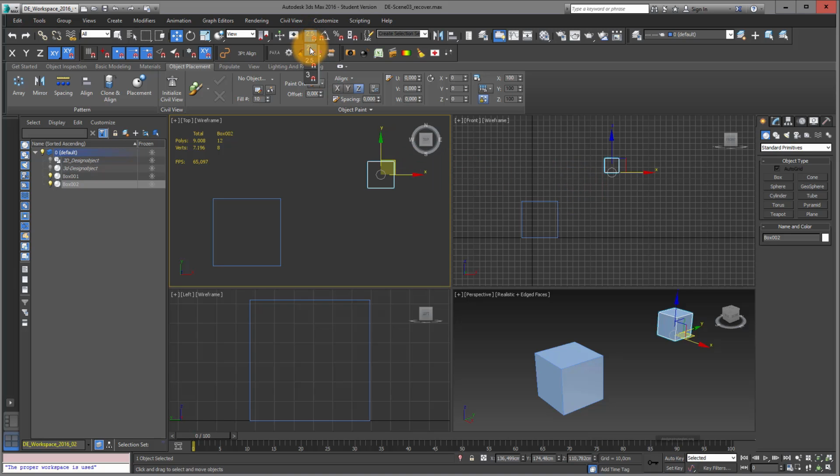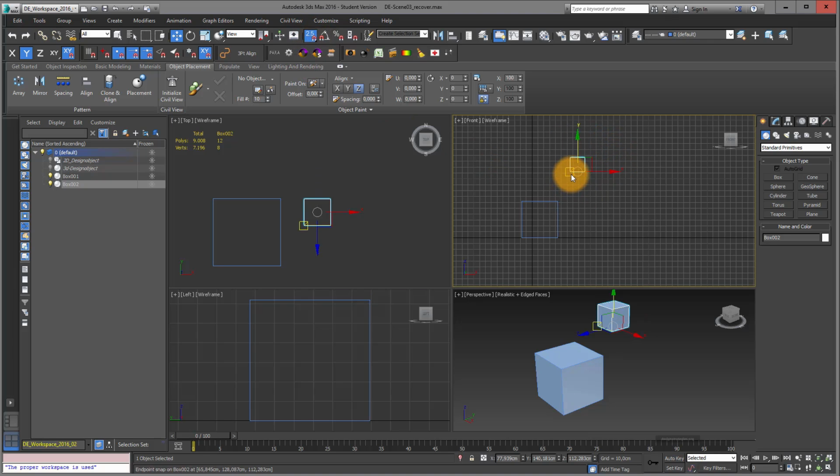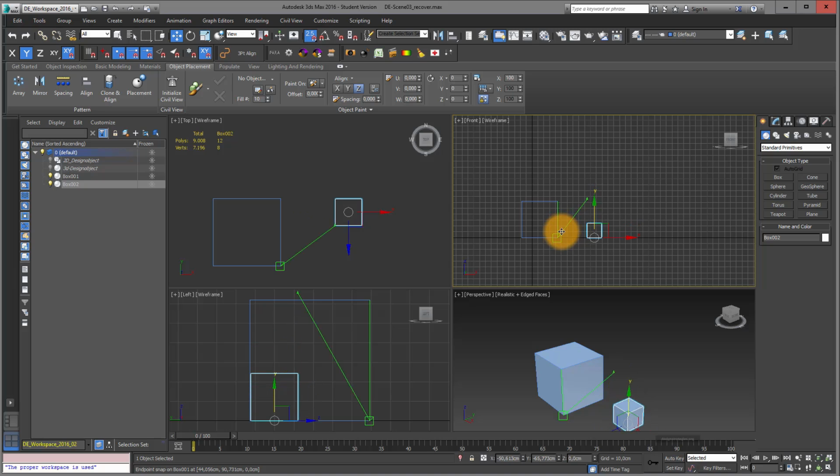If you go into the 2D mode, which I hardly ever use, then you can see it only works when the objects are exactly on the same level. So let's move back to my 2.5D mode. I just right mouse click my front view, select this point, and I just select my y-axis, and only my y-axis and the corner point at the lower part, align it to the bottom.